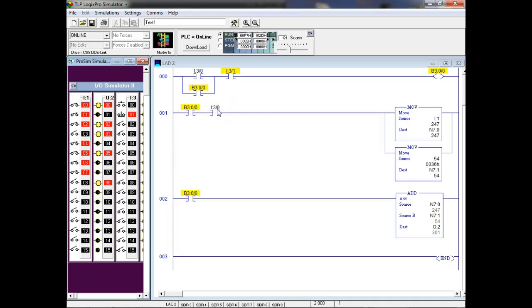This rung right here, I don't need to use that, because I made a common mistake. I stuck this in there so we can make this condition. You notice what I did? Yeah, I made my start button. And this is the type of error that, when you check it, it won't give you an error because it's perfectly valid. Right? You understand that? So we got it in the right syntax, the correct way of writing, right? But when it compiles over, it won't work. Everybody okay? I have to hit the start button and go both of them.